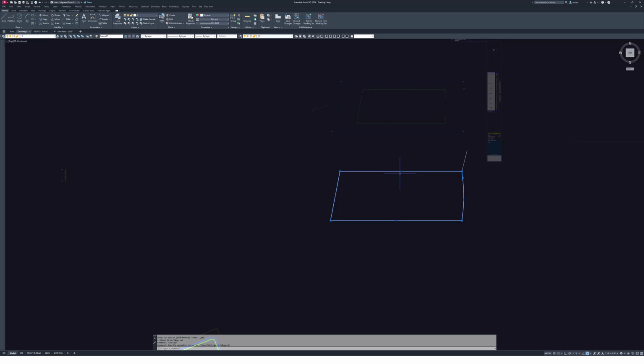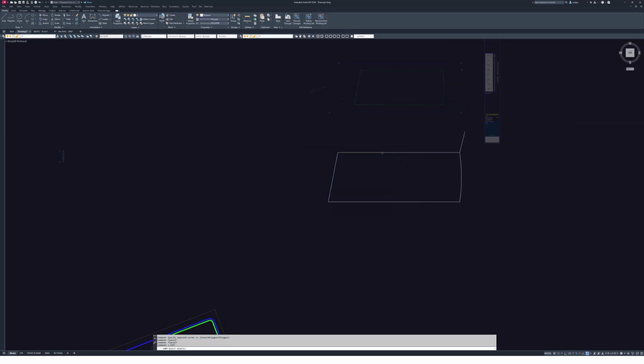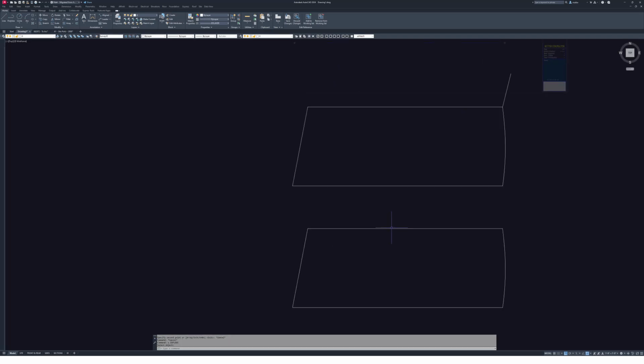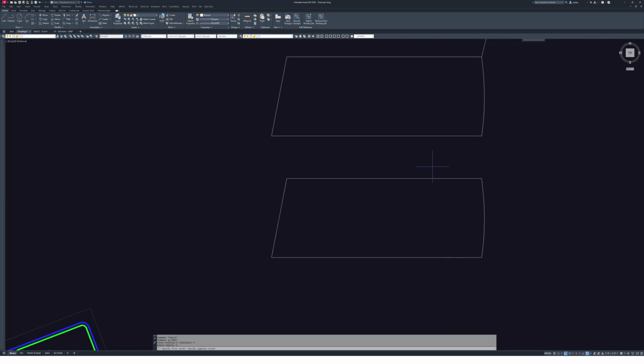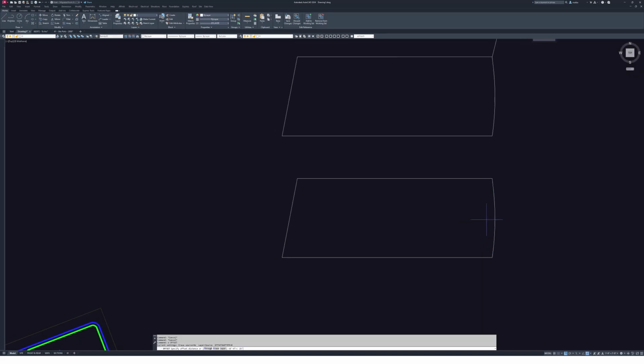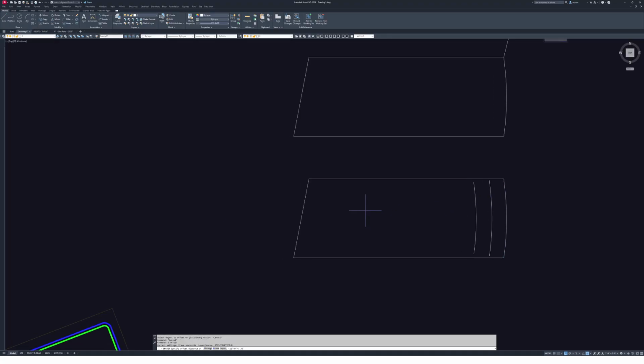Now this is already a polyline, so just to make my life easier, I'm just going to copy one down. Now I'm going to copy it down 100 feet so I can explode it, and then I know I need to poly join these two guys again because we're going to offset 25 feet for that setback. And we also saw that we have a 12-foot utility easement, so we'll throw that in there. Offset 30 feet, offset 10 feet.